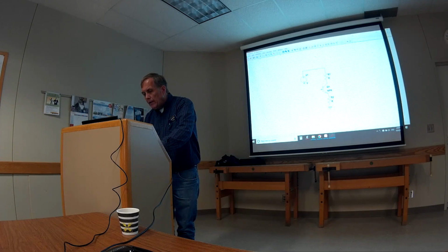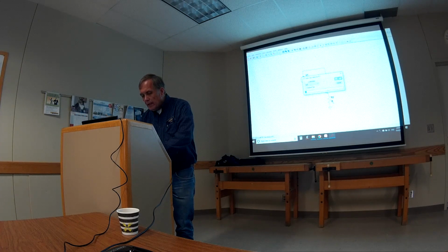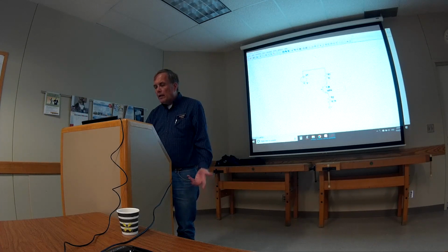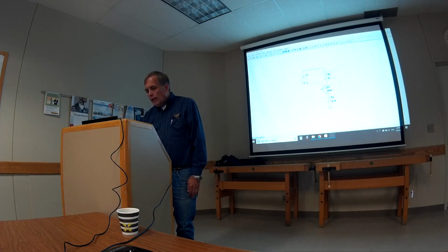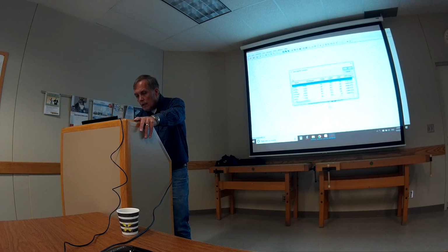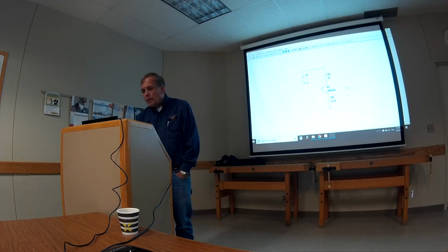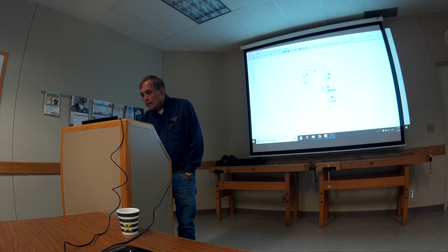Now, how do you specify a resistance value? We did that before. We click on that, and we say I want a 4.7K. And the NPN: how are we going to get what kind of transistor that is? Well, if you right-click on that, you say pick a new transistor, and then you can go up to the part number to put in order here. And you look down the list, and it happens to have a nice model of a 2N2222. So you say, okay, you could have used a variety of them, but that's just a nice basic one. And I'm just going to do a couple more parts here, and then I'll stop and go to a fully built one.